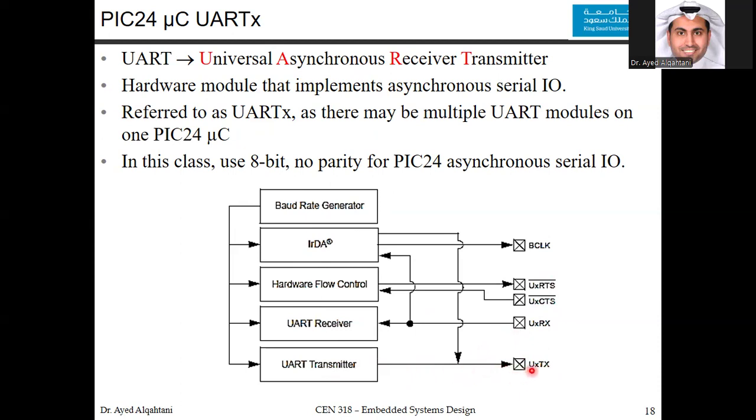You are transmitting to a receiver somewhere, and you get some information back from the receiver that tells you, hey, I'm ready for you, transmitter, start transmitting. This signal would be the clear to send. The receiver tells the transmitter, you're clear to send, come on, let's go, so it starts transmitting. Similarly, you have the same scenario between the receiver and the request to send. That's called flow control.